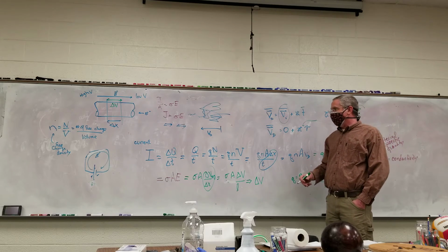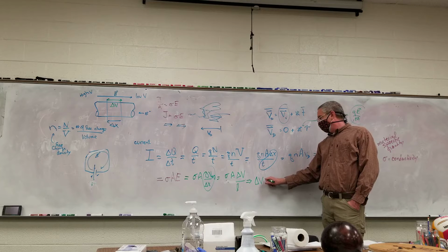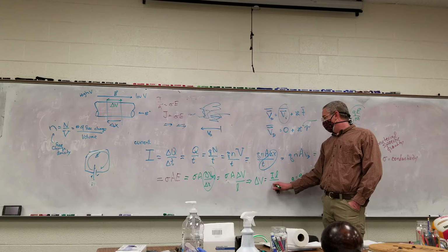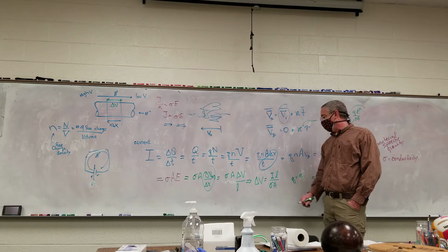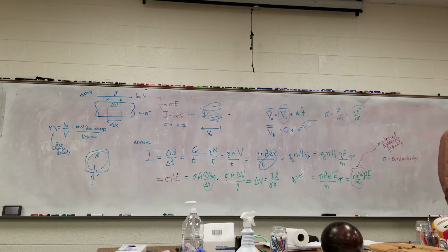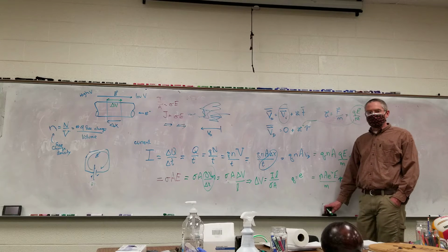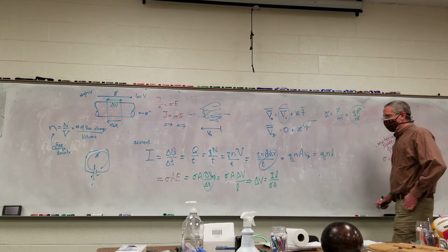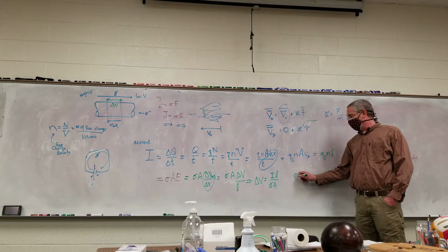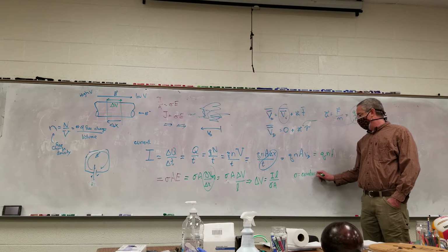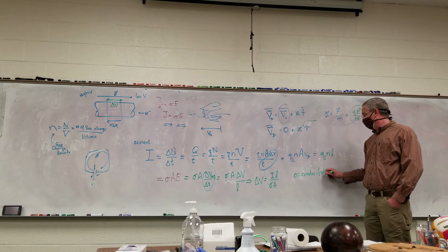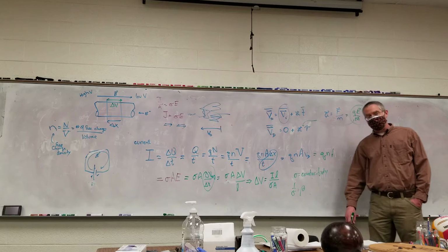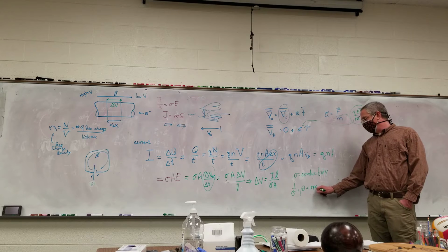So the voltage across the battery or whatever segment I'm looking at is equal to my current times the length of the wire divided by sigma A. This is still not the traditional form that you tend to see this equation. They decided to take it one step further. Sigma is conductivity. And the reciprocal, symbolized by the letter rho, because we don't use that enough, is known as resistivity.